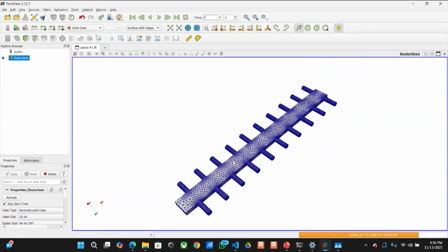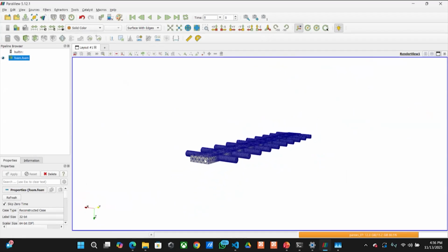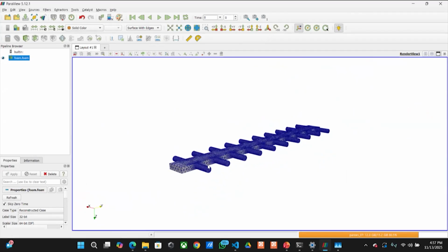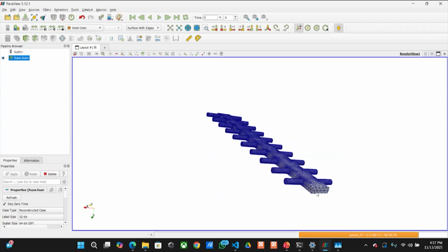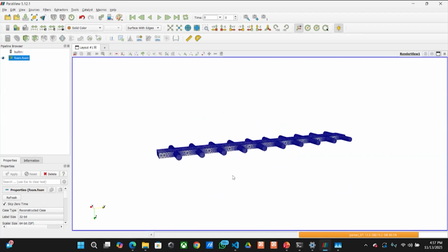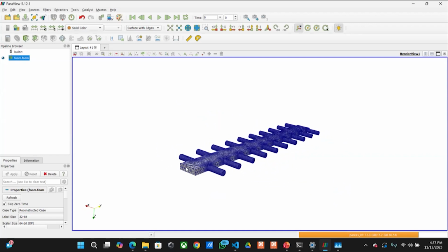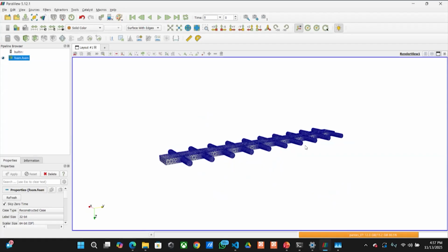The only thing we need to take care of is that while we are developing the mesh in ANSYS, at that time only you have to specify the named selections. In ANSYS, you have the named selection parameters where you have to specify the names of your particular regions. Let us say I named it inlet or outlet.